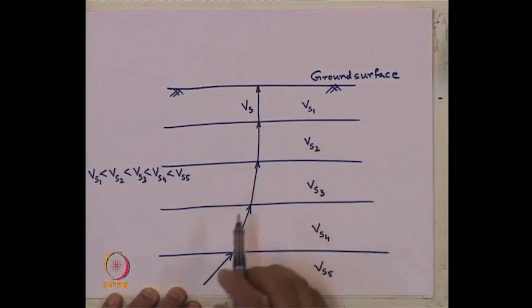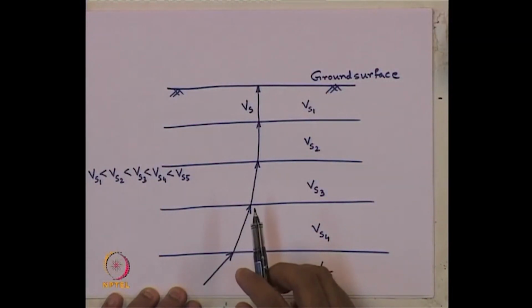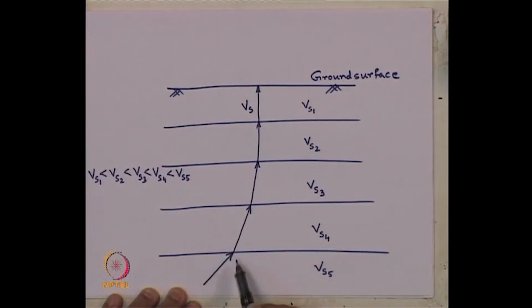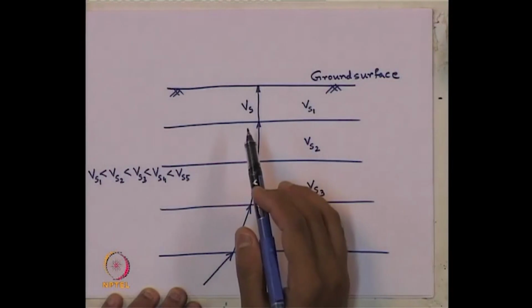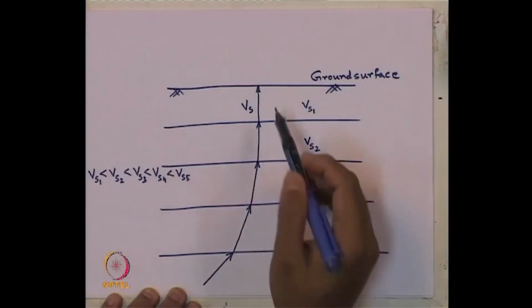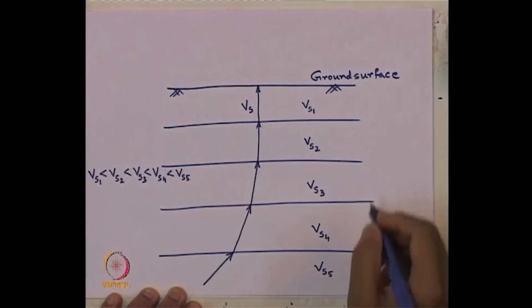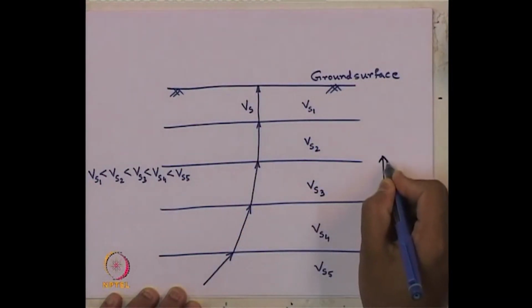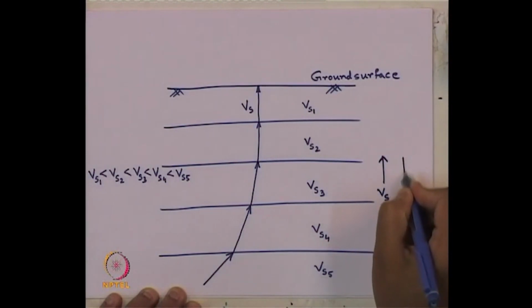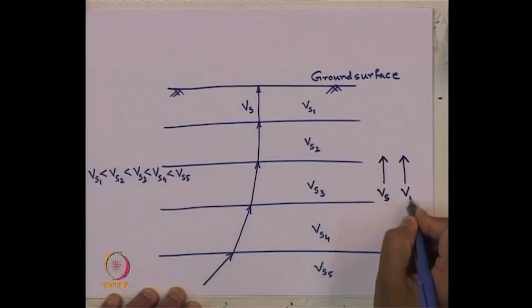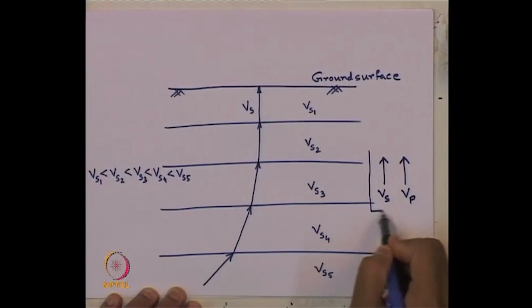So, that is why in many of our design problems, we hardly take any inclined nature of the waves. We generally take, whether it is shear wave or primary wave, when we are considering near-ground problems, in that case we mostly consider it as vertical. So, we consider a vertically propagating wave Vs or Vp in the design.